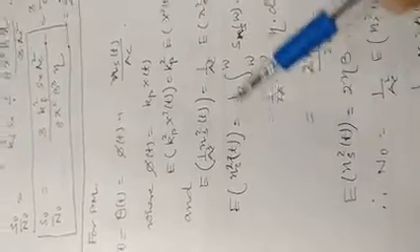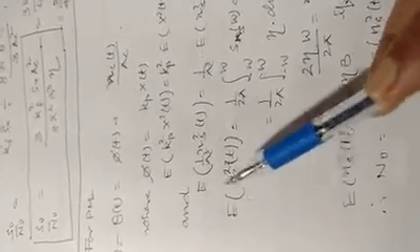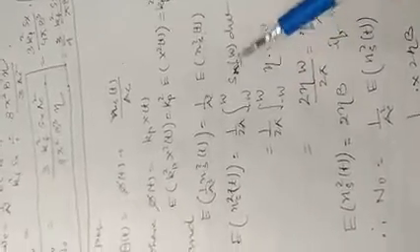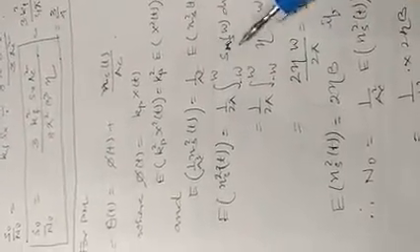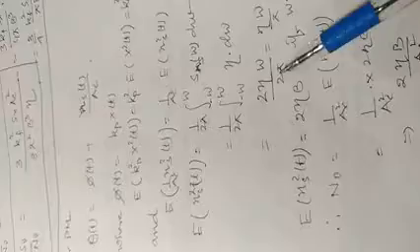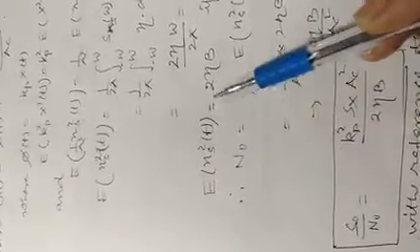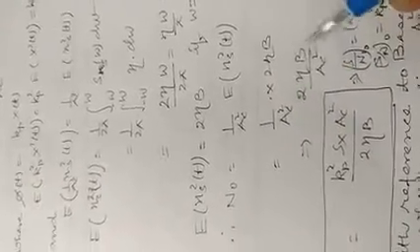And if we calculate the energy of that quadrature phase component, that is the average power, E of n square s of t is equal to 1 by 2π integral from minus W to W of SNS of omega d omega. And here SNS of omega is nothing but eta, so we can integrate it and we have this formula 2 eta W divided by 2π. The 2 and 2 are cancelled, and here we can write W equal to 2πB. So we can get this formula, and the output noise power is equal to 2 eta B divided by Ac square.